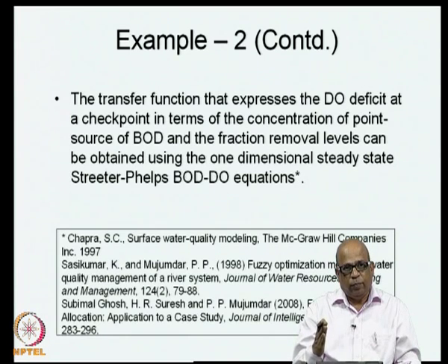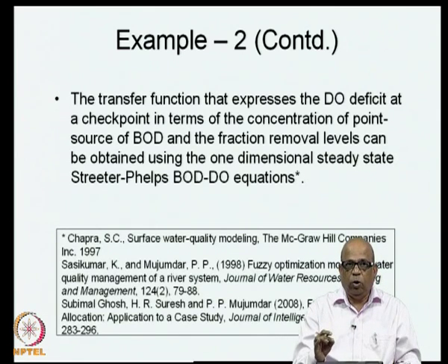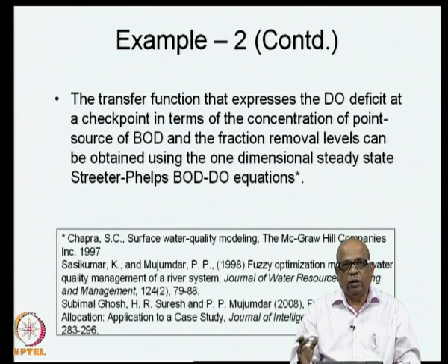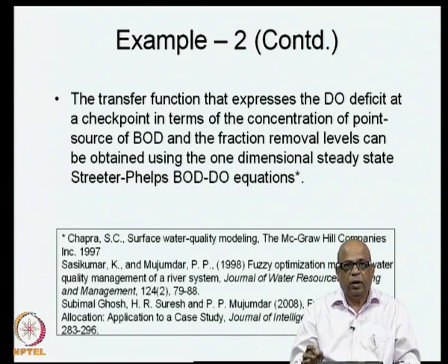Because we are talking about only one pollutant, namely BOD, and only one water quality indicator, namely DO, the dissolved oxygen at a particular location can be determined based on the BOD loads coming upstream of that location, using the classical Streeter-Phelps equation.